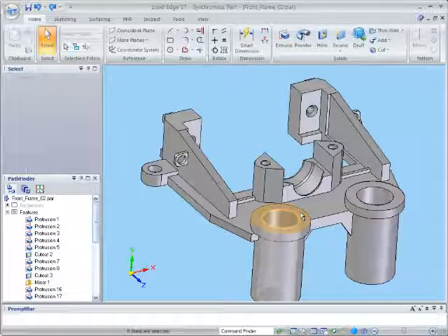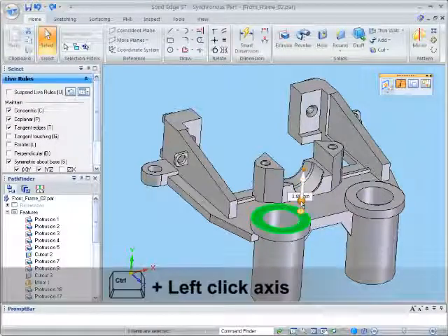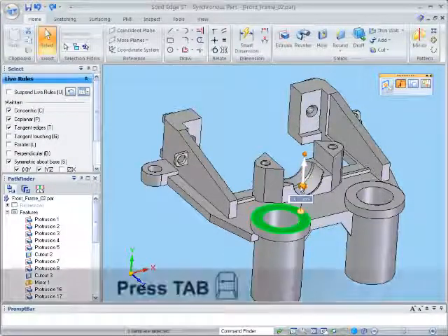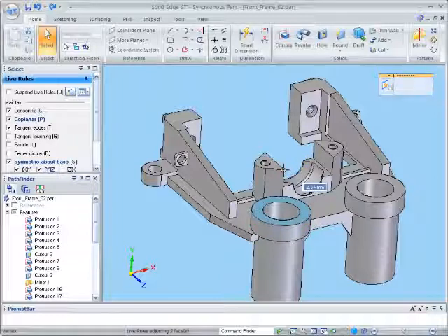Finally, this is how the steering wheel is used to move geometry to a set distance from other geometry or reference point. First, the steering wheel is indexed a set distance from the face being moved. Then shift-click the primary axis and use the tab key to set the focus to the dimension box. Key in 6mm and click to accept.